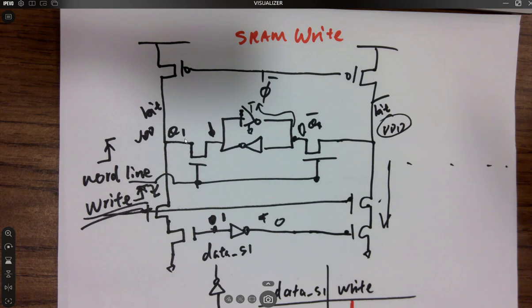All right, and if you describe a latch in that digital design description language, Verilog, it won't synthesize the SRAM for you. This is designed by human hand, right? And FPGAs don't have these latches. If you write it in Verilog, it won't be able to synthesize this kind of 6-cell thing for you. If you write a description and synthesize it, eventually it becomes a D flip-flop.